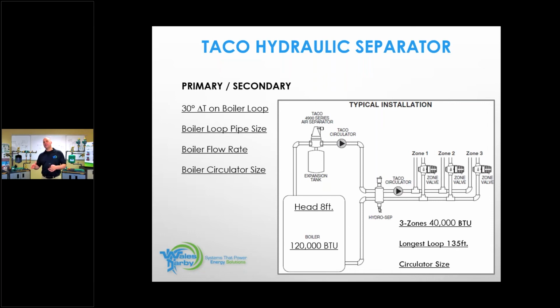The problem is, we're really only going to see those temperatures on a design day. So the majority of the time, those deltas are going to be lower than what they will be on design day. And as we talked about last week, 3% of your heating season, you're running at design conditions. So you don't have a big opportunity to see that.